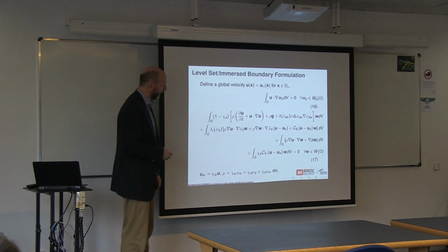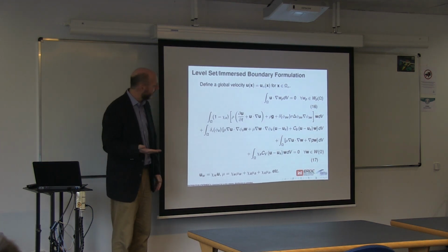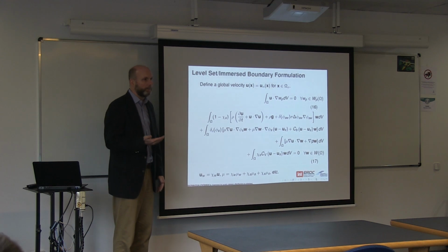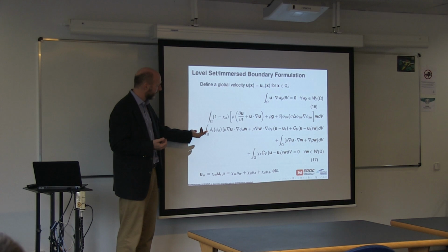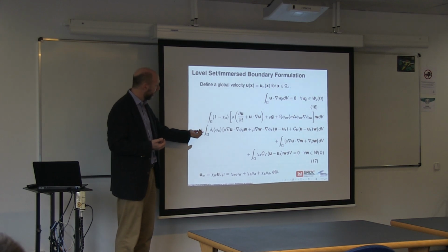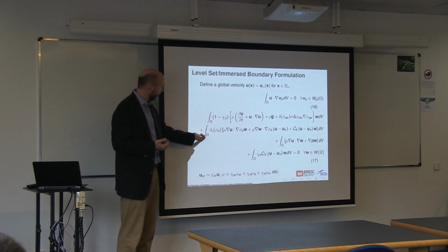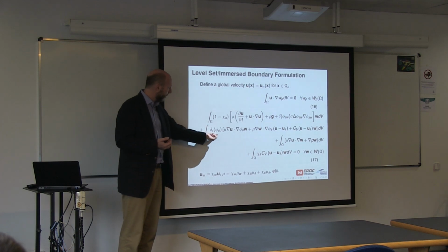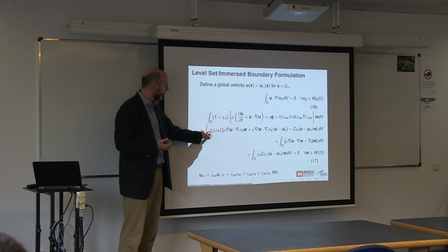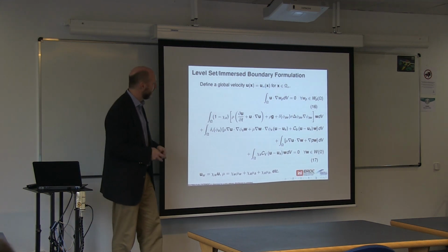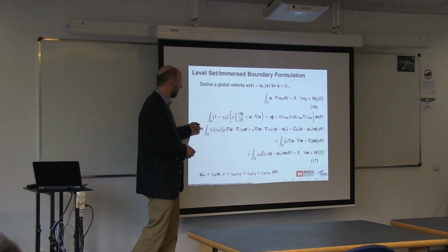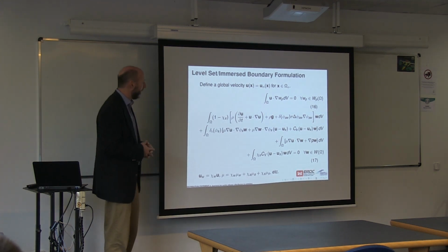The thing that we don't do that many immersed and embedded methods use is that we don't do boundary integration. Instead, we use another trick from the level set community where we convert a boundary integral to a volume integral by multiplying by the Dirac delta function. In this case, it's the smoothed Dirac delta function of the signed distance field. And so this gives us weak imposition of the no-slip condition at the solid phase.